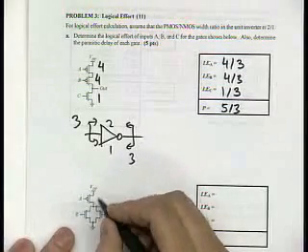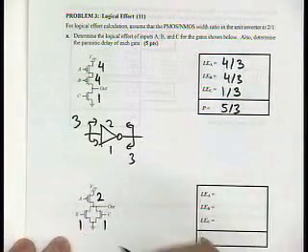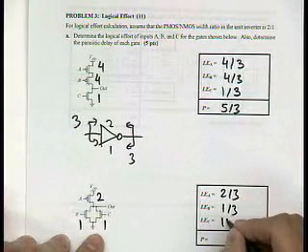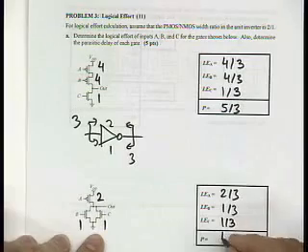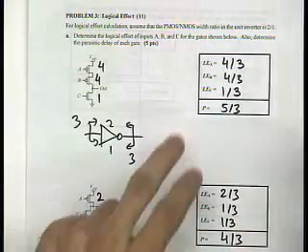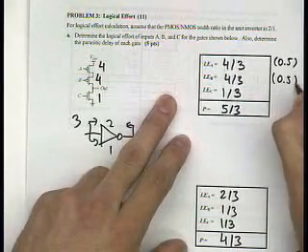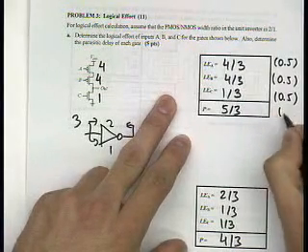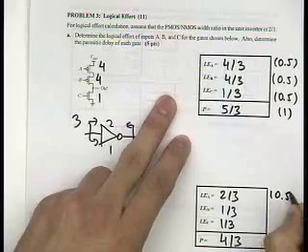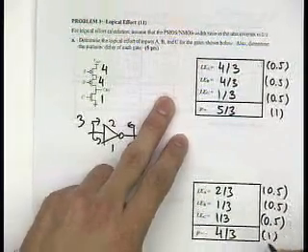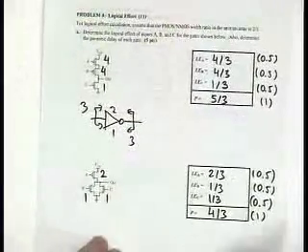This is a similar story, just the PMOS, you have 2, 1, 1. So you have 2/3, 1/3, 1/3, and then the parasitic delay was 4/3. So the distribution of points was 0.5, 0.5, 0.5, 1, 0.5, and 1. And now a little bit more complicated example.